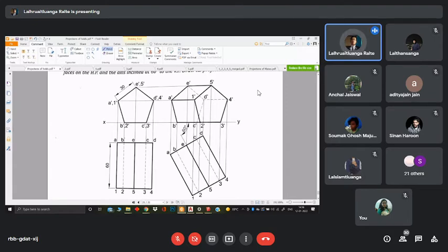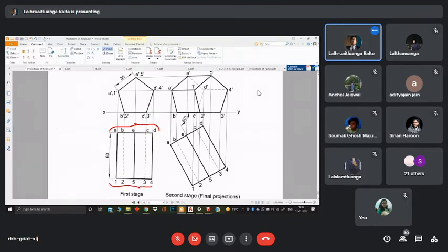All right, so whenever we do our annotations, we always go for the alphabets on the lower side and the numerals on the higher side. Here you will say that's quite the opposite. It's not the opposite; lower side in the sense that the face which is closer to the reference plane should always be annotated with the alphabets, and the face farther away from the reference plane will be annotated with the numeric annotations.